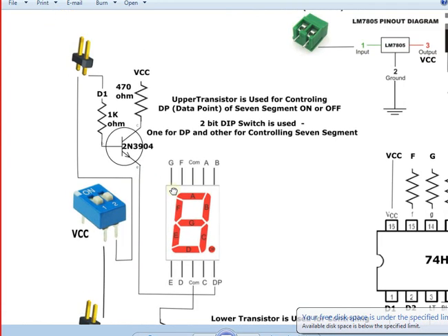So what I have done over here, I am using again a switch transistor which is going to turn on this DP through that transistor, and this time I am sourcing the current to DP. This is very important over here. Since this transistor is connected to VCC, there is a 470 ohm resistance. Now, why have I used a 470? Why have I not used a 330 ohm?